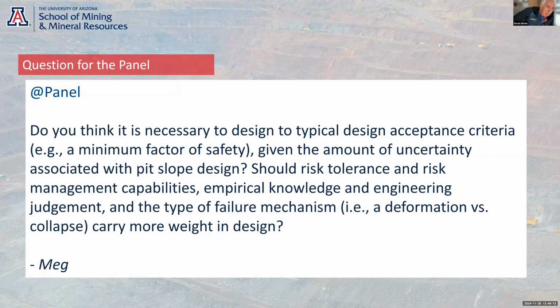I guess the only problem we all face is that we can calculate a factor of safety, but you can't measure it. And you can only measure the performance of the wall. And if you're having to deal with minimum amount of disruptions to the mining operations, do you really care about the factor of safety as long as the performance is acceptable, targets have been met? So do you really care what the factor of safety is?